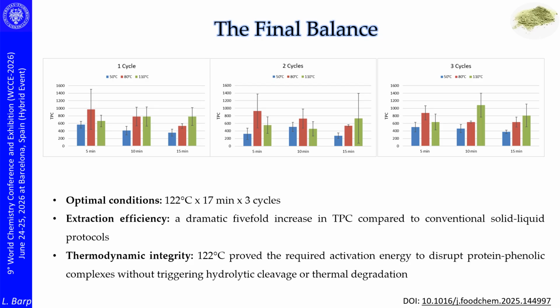The mathematical model converged at an optimal temperature of 122 degrees and a static extraction time of 17 minutes for 3 cycles, under a stable system pressure of 100 bar. A 5-fold increase in total phenolic yields compared to conventional solid liquid reference protocols was observed under these conditions.